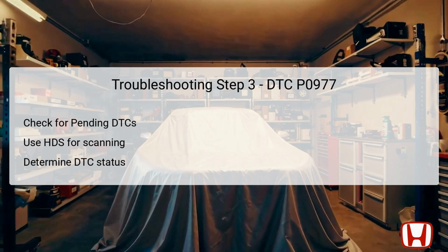If it does show up, this indicates that the issue may still be present, and you should proceed to the next designated troubleshooting steps. Conversely, if it does not appear, you will need to execute additional testing procedures to figure out any underlying issues that could lead to intermittent failures within the solenoid circuit.